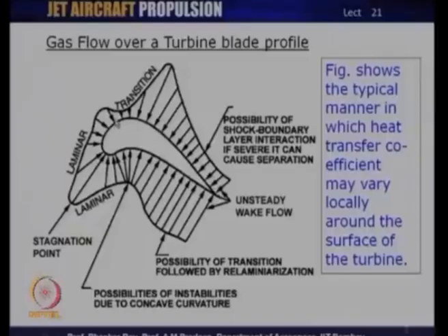In a laminar flow, as the definition of laminar flow is known to you, there is no mass or heat flux across the laminars of the flow, which means the laminars segregate each other, and hence those laminars do not allow any high temperature to flow in from the hot gas into the blade. However, at the stagnation point here, when the flow comes almost to a stagnation, or theoretically to a stagnation, the entire hot gas kinetic energy is now available in terms of potential energy.